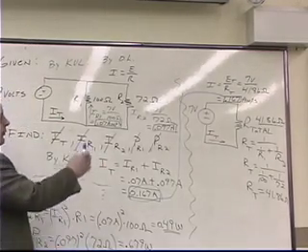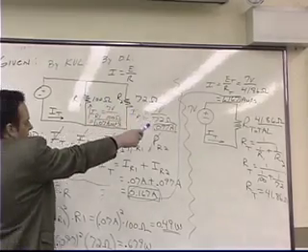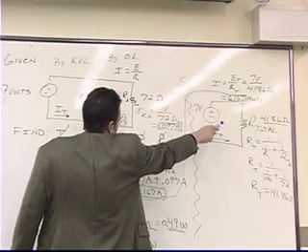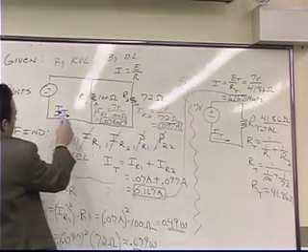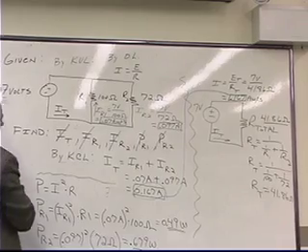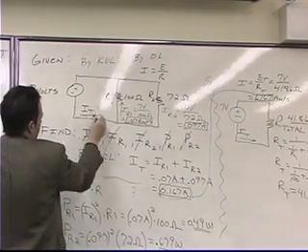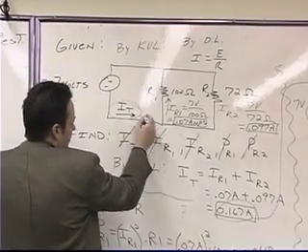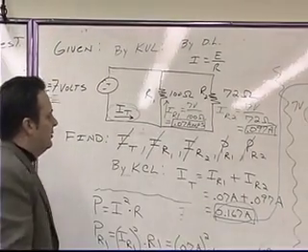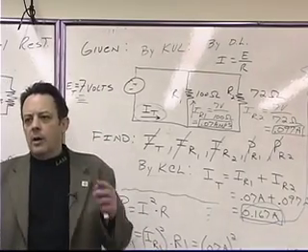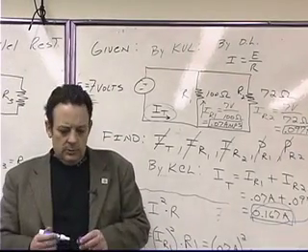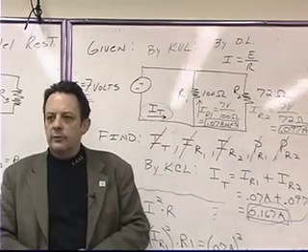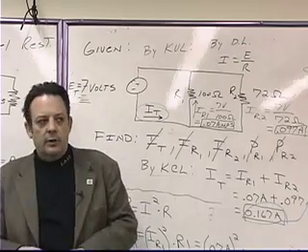If I had found the total amperage being drawn by the total resistance of the circuit, then I would know this. This would be the first thing I would find out right here. And then using this current, I could use Kirchhoff's current law in combination with the current divider to find the current in either one of the other two branches, and then subsequently the power.